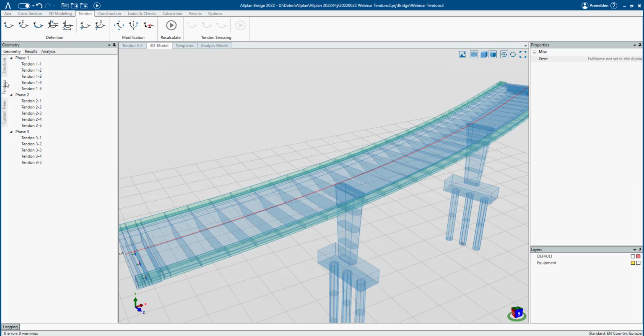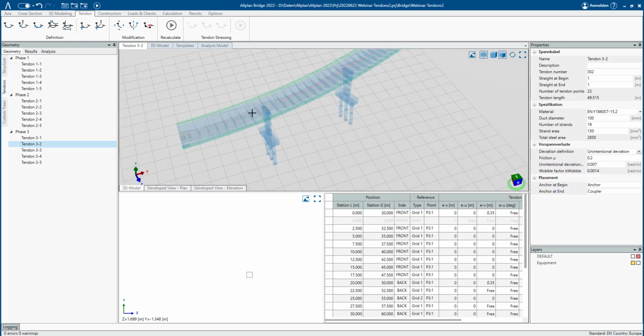So much for this topic here on this example for the plate bridge. As you can see, the way of modeling is quite the same as for link girder or for prefabricated elements or for normal 3D modeled elements. You define some elements, you can copy them, you can mirror them, you can adjust them with the constraints, you can put eccentricities on it. So things are quite quick then to create tendons out of it. Like in my case here, 15 tendons in about 5 minutes.